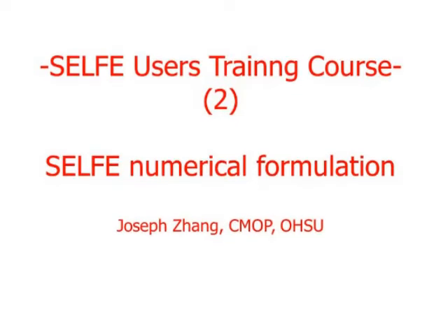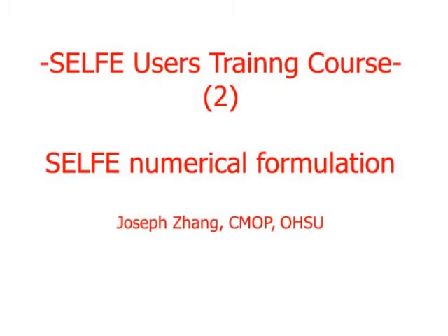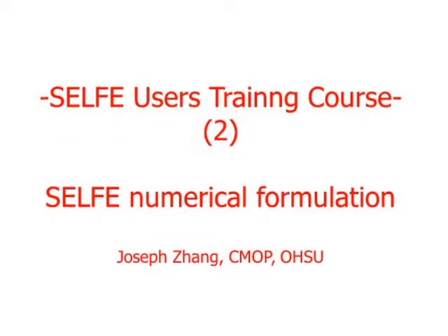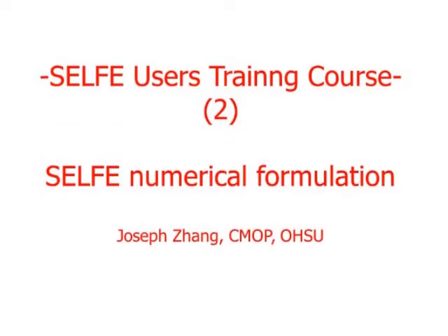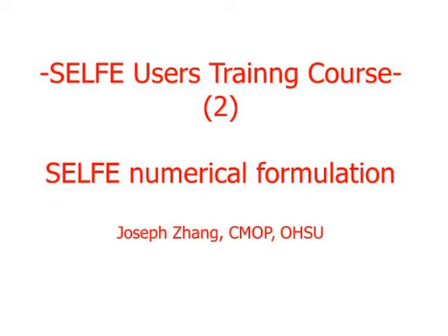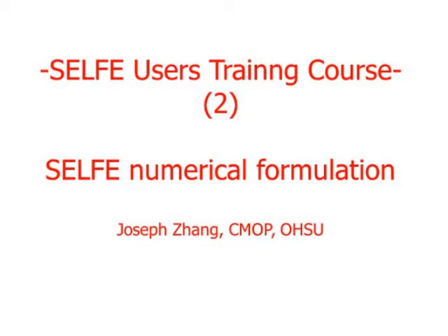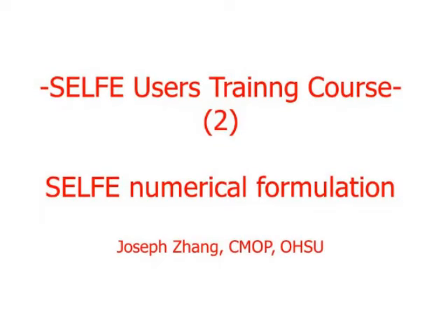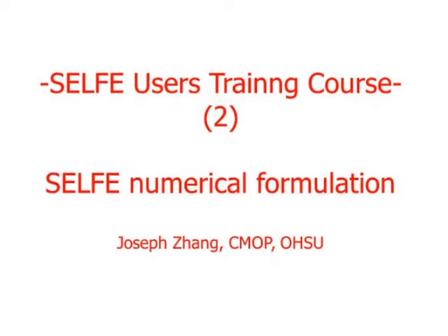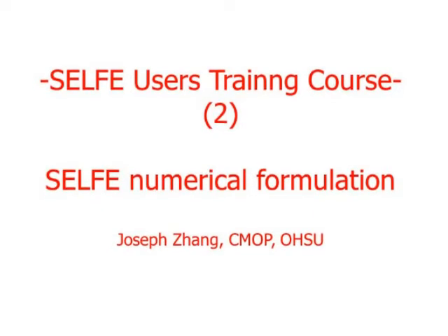Next slide, 25. I mentioned that inundation, the wetting and drying, can be treated very easily inside SCHISM. There are actually two algorithms inside SCHISM to deal with wetting and drying. After elevations are found, you need to update the z coordinates and the free surface positions for the next time step. There are two algorithms to do that. The first one is the simplest. You just go through the element sides and nodes at the end of each time step and update their indices based on the newly computed elevations.